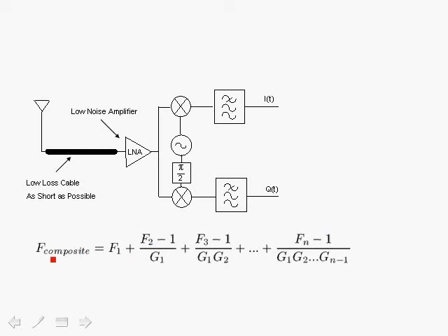So if we look at the total noise figure, we see that we need a low noise amplifier with a very low noise figure and a high gain, and then we can also go through the various stages. For example, the mixer usually has attenuation, and you have various gains within the receive chain and filtering going on, and all of those have high noise figures. But as this expression shows, the key is the noise figure of the LNA and the gain of the LNA.